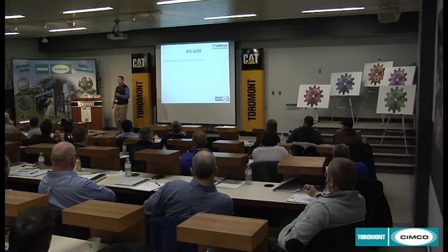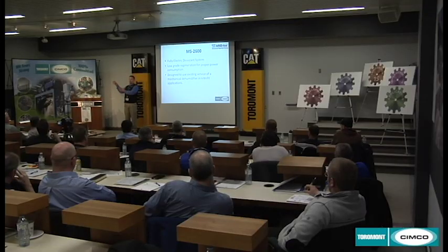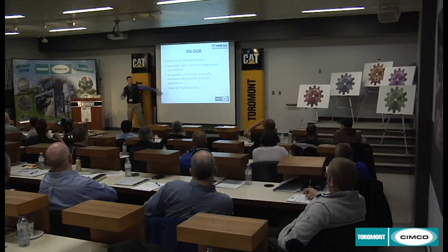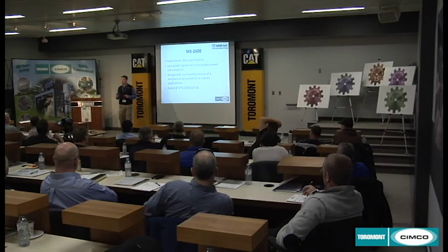We designed it as an electric system, uses PTC electric elements. It's a low-grade energy, and we did that intentionally because we wanted it to fit the energy profile of what that existing mechanical cool reheat system would have, so that we could be roughly the same power consumption, so you don't have to bring a new power service over there if you're retrofitting one of these in for your mechanicals. We also designed it to be very similar in dimensional and weight, so that it could fit on the same stand with very low modification costs to you, the end user.